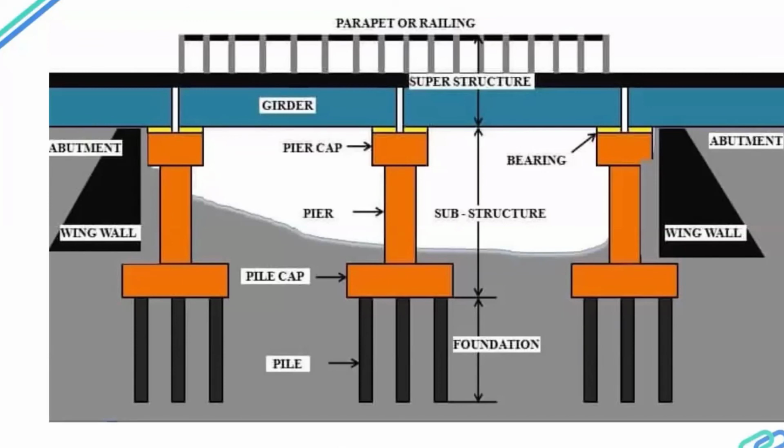And then of course there is pile. Typically these piles would be 20 to 30, 35, 40 meters into the ground. So they have to be bored into the ground, and many a times the contractor would come up and say that there are concreting issues, there are honeycombing issues, what to do now, and the pile does not pass the pile load test. So there are so many challenges that as a designer you need to face during the construction also.